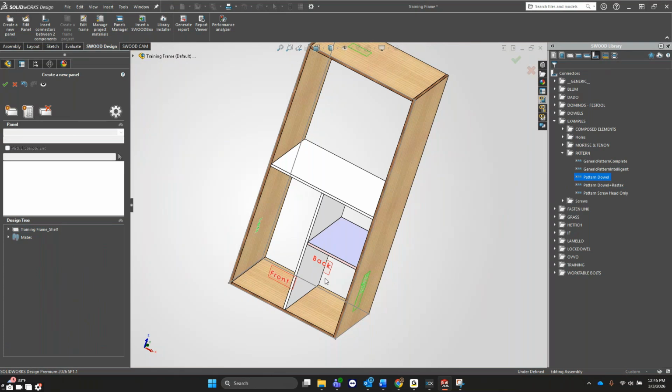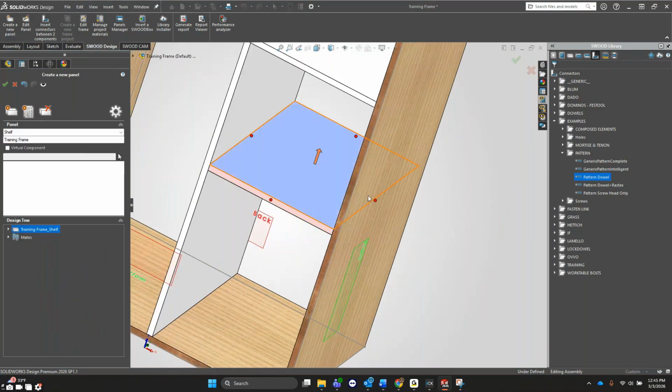No, I had a question about the plane. Okay. Would you be selecting the, for example, the right or front or bottom plane to position this new plane, or can you reference the face of a panel? When inserting a panel or a plane? A plane that you're speaking of. It could be either one. Okay. Generally, I'd recommend basing it off planes because the faces of these panels might change position, based on what material you use or how you have them set up. It's usually more reliable to reference off the planes, I would say. Okay.